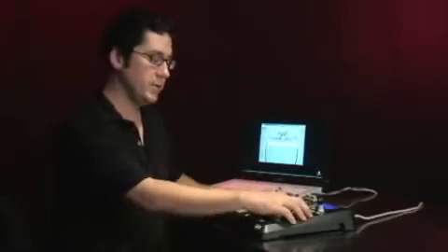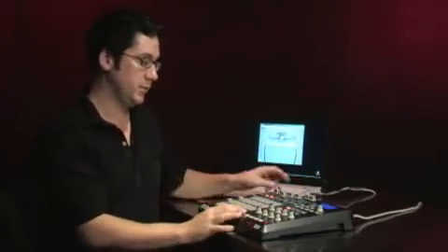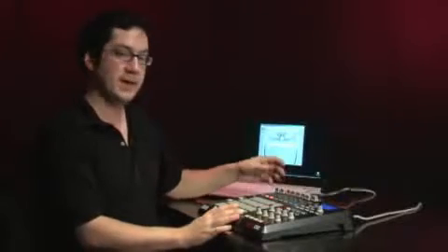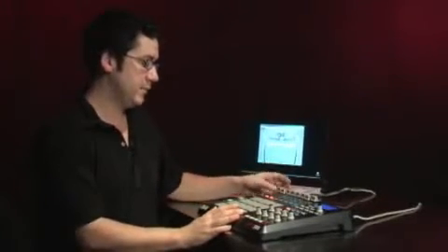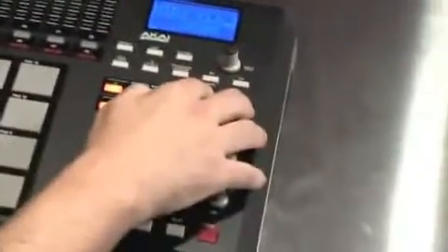There's a preview button here too to the right of the controller banks. The preview button will allow us to change the value of a controller but not commit to it. So if you've set all your control values up to here and then you change your banks on your software, and the value of those controllers are now down here, by moving the controller, it's not going to snap the value all the way down. So you can press the preview button, move the controller, and it doesn't commit to it. That way you don't get the snapping effect of the data in that particular controller.